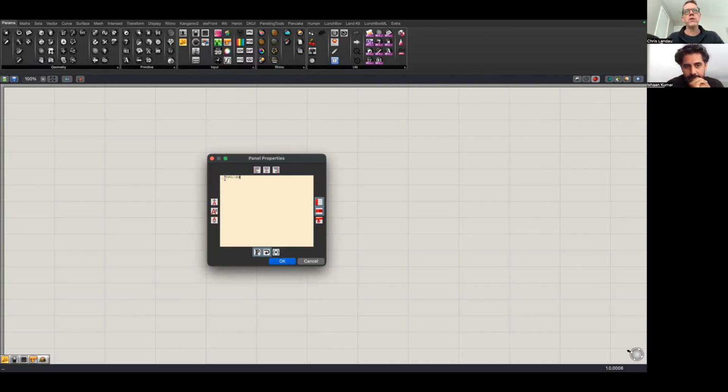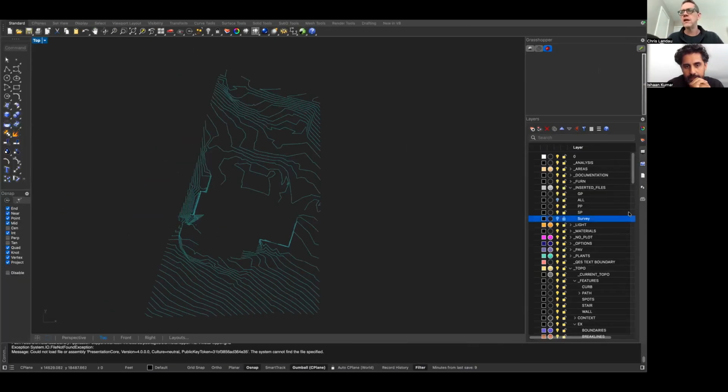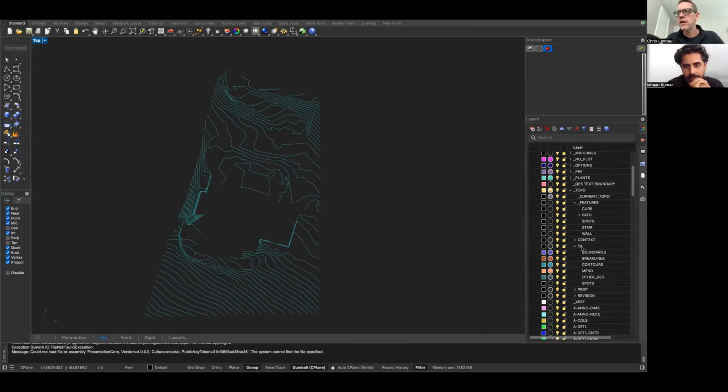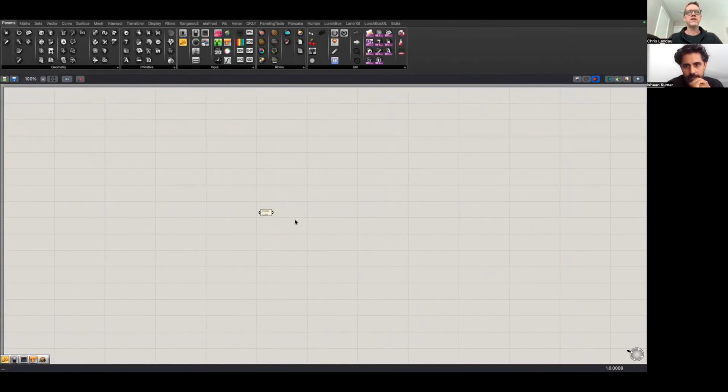Maybe we can turn those things on real quick. So we've got topo existing. This is how, when you have sub layers, you do these two colons. It's the parent name and then the child name, and then you say okay. What that does is I'm looking for this parent layer here, so it's under topo and it's existing. And all these things here are part of the Geo Set. The Geo Set allows you to draw different geometries on that layer so that it's just importing all that stuff. We've already moved the contours to that layer, so that's great.